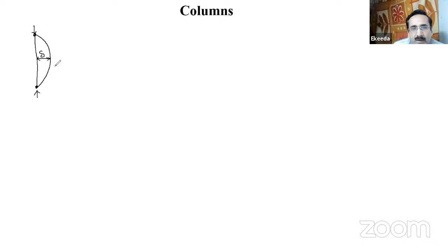Why are we saying buckling? Because there is a slight difference between bending and buckling. Bending is a fixed deformation. Suppose this is a beam and a load is applied here. This is bending because we know where it will go, it will deform in that direction. But in buckling we don't know in which direction it will buckle. Mainly it will buckle in the direction where the moment of inertia is minimum. The buckling direction depends on moment of inertia or minimum radius of gyration. That's why we name it buckling rather than bending, but it is actually bending.